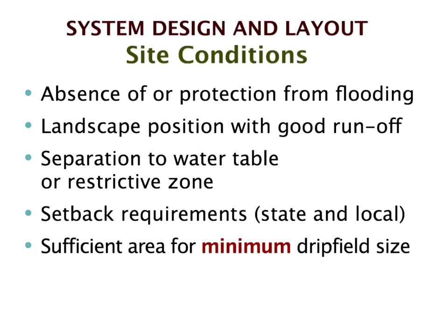As I was talking about a few minutes ago, if the minimum drain field size just happens to exactly fit the area, and particularly if this is a single family home, I would be cautious. Not that I'm talking of any individual, but people are known to look at the area and then decide that's the minimum application rate, as opposed to looking at the soil, deciding the application rate, and then coming up with the area. Sometimes it works out okay, and sometimes people have been known to push it a little bit.